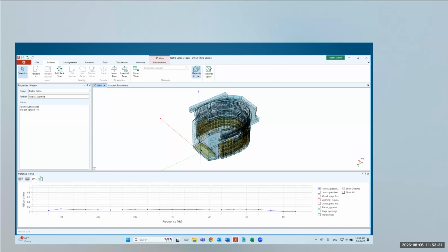Yeah, if you go into the filter for that loudspeaker, you will see that in the conversion from EASE, a third octave spectrum from 100 hertz to 10 kilohertz was brought in. If you delete that, that will get rid of the roll-offs that were there.